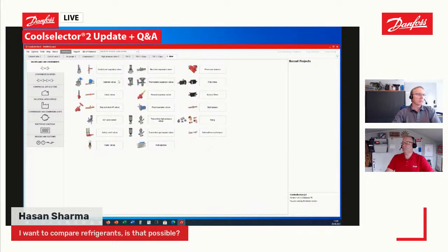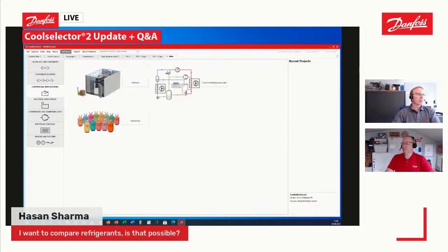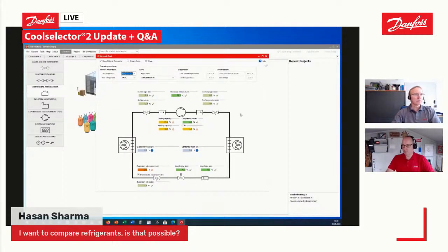What you can also do is go to the commercial applications. There is a part called the retrofit tool, and this retrofit tool allows you to compare two different refrigerants for the whole system. So if I just keep the inputs here, R22 may be replaced by 407C at a normal temperature or intermediate temperature application.